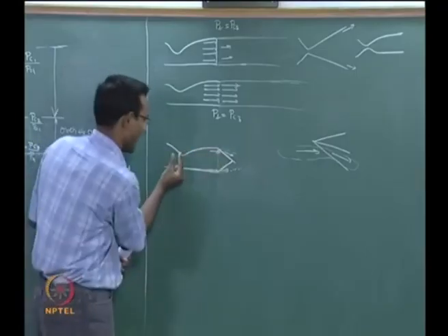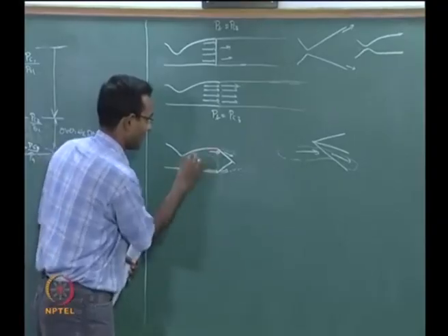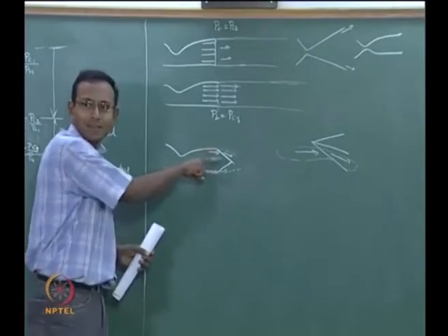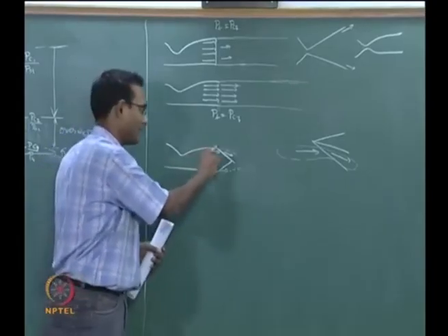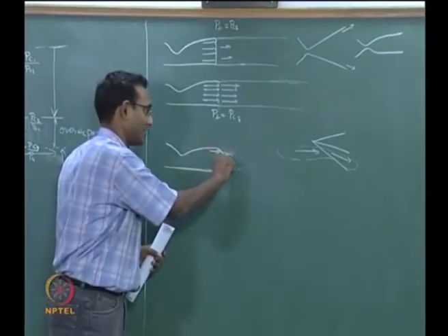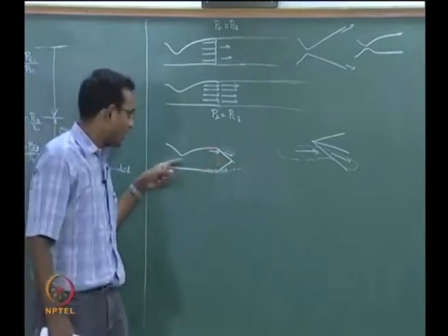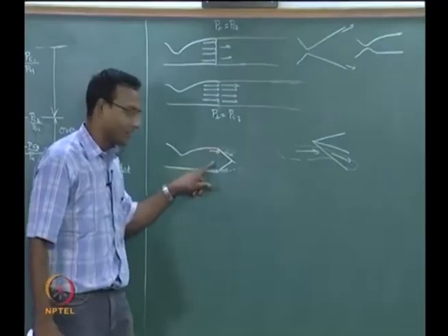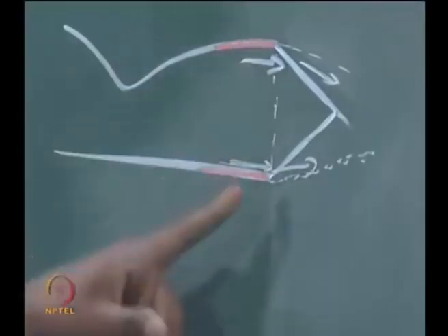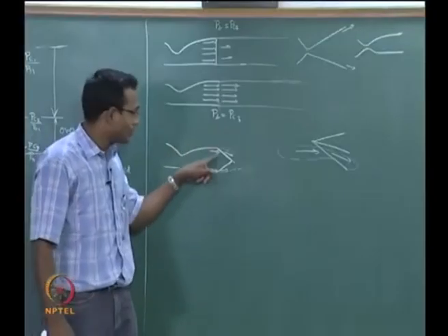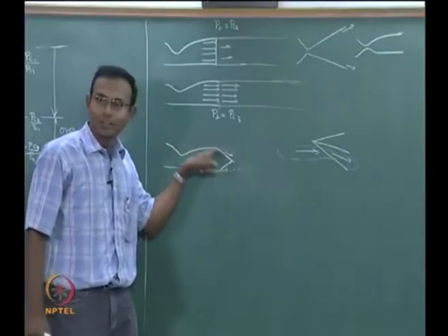I am thinking about one slab of fluid going like this, it is increasing in size as it goes here. Why does it increase here? It is expanding, it is increasing in Mach number, and when it goes here it is suddenly having to change in size. All this time we talked about one Mach number at each location axially. After exit I cannot talk about that. Why? Because it is a 2D problem. I have introduced a 2D component here.